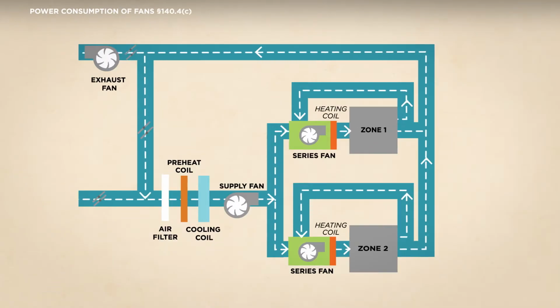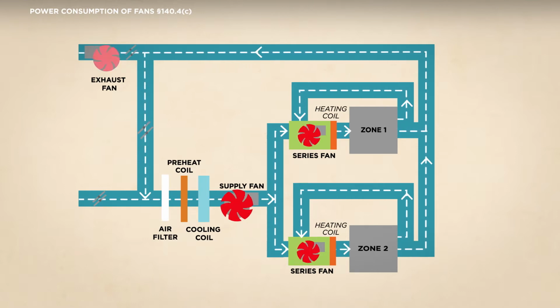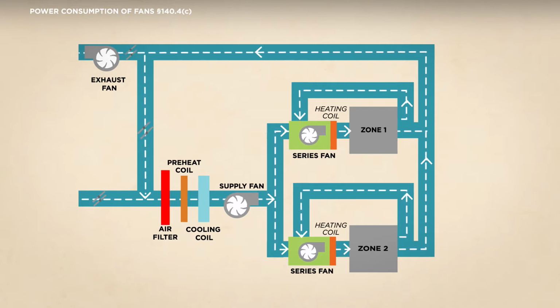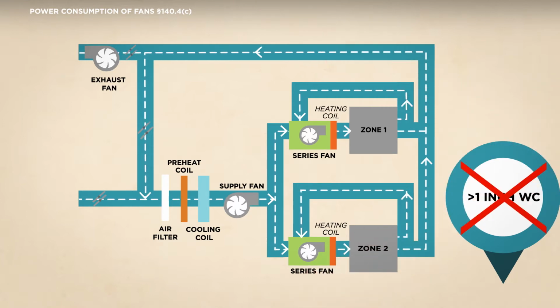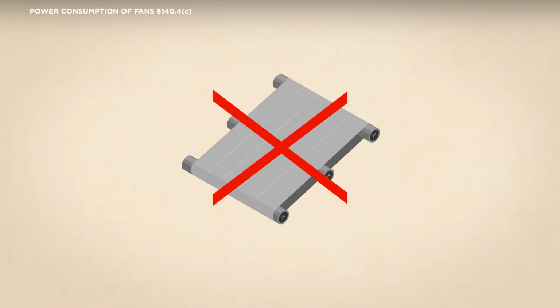The energy standards have specific requirements regarding the power consumption of fans used for space conditioning. Total fan system power consumption is calculated by summing the power consumption of all fans needed to operate the space conditioning system. However, total fan system power consumption excludes additional power demand caused by air treatment or filtering systems with final pressure drops more than 1-inch water column. Only the horsepower associated with a portion of the pressure drop exceeding 1-inch water column can be excluded. Total fan system power consumption also excludes fan system power caused solely by exempt process loads.